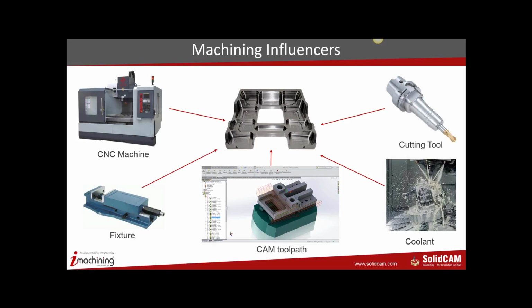I talked about another thing, acceleration and deceleration. Your acceleration and deceleration has to be very fast, because I told you that when you looked at some of the challenges, we have this unique ability of work hardening. So you have to be very quick to re-enter the zone much faster than you would do with the same machine cutting steel.